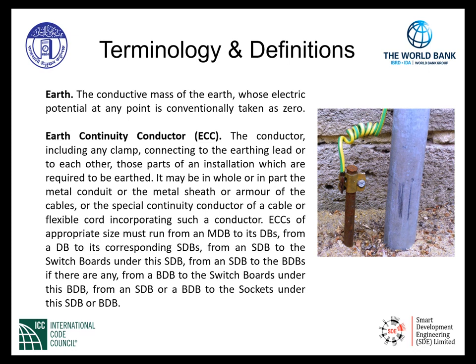or the special continuity conductor of a cable or flexible cord incorporating such a conductor. ECCs of appropriate size must run from a MDB to its DB, which are distribution boards, from a DB to its corresponding SDBs, and from an SDB to the switchboards under this SDB, from an SDB to the BDBs, if there are any, from a branch distribution board to the switchboards under this BDB, from an SDB or a BDB to the sockets under this SDB or BDB.